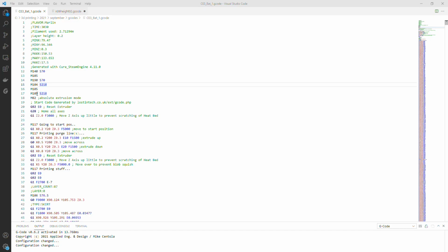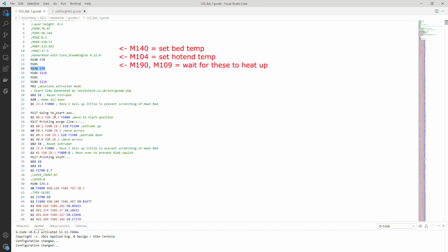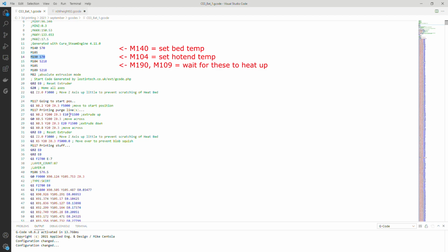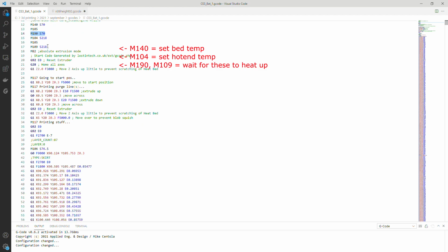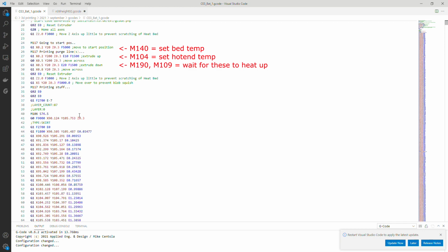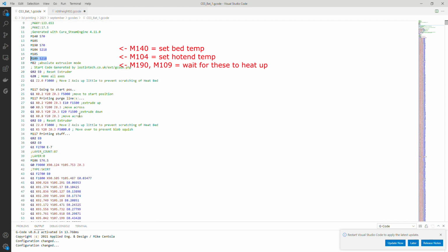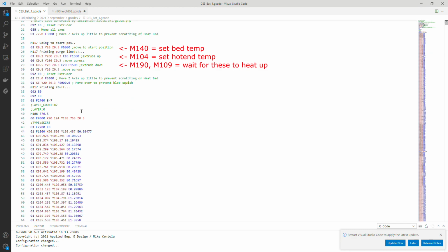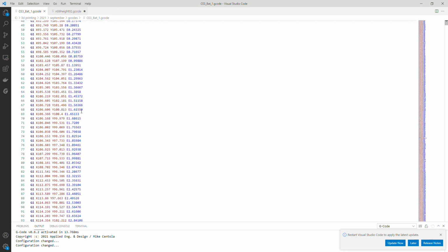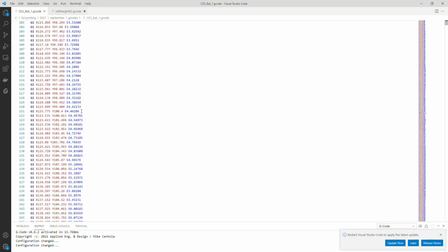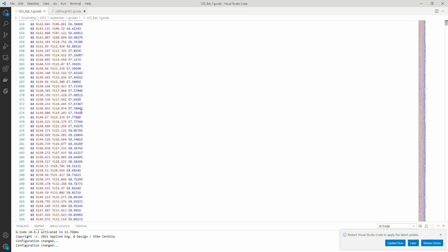Now first up, I want to show you some G-code. G-code is astoundingly simple. I've shown it many times before and I've always explained what it's doing, but because this is a vast solid block of data, it looks more intimidating than it really is. If you ignore most of the parameter commands here, for example those that change attributes of the printer like the hot end temperature command here, once you pare it down, for 3D printers you usually just end up with a lot, and I mean a lot, of G1 commands.